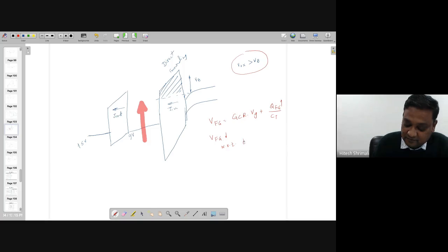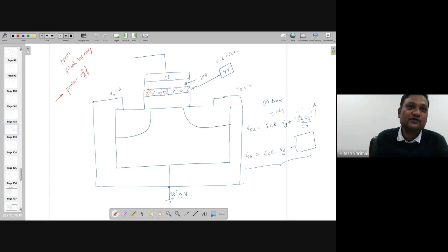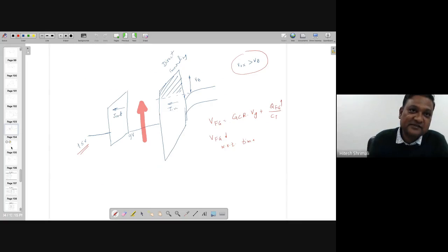And the gate voltage is at 15 volt. You don't change it. Look, these trap charges do not happen in 0 seconds. When you are writing it, it takes some time to get it trapped. The voltage will remain at 15 volts. Then it's CC by CT only, right? This GCR is nothing but CC divided by CT, because the parasitic capacitance does not change. So because of this increment in QFG, but with negative sign, this VFG is getting reduced.